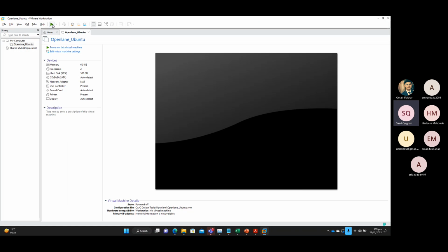It should work. Next step is to, once you have created a netlist, simply press simulate. It should take some time. Now click simulate next to netlist. Wait a few seconds and you want to see.